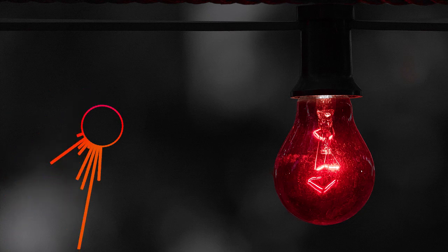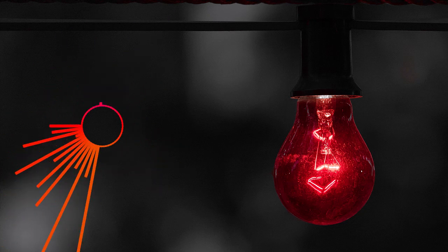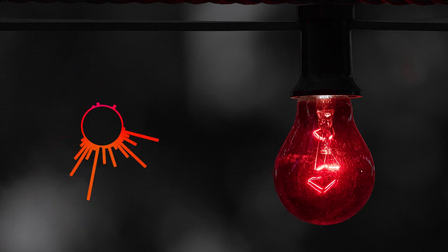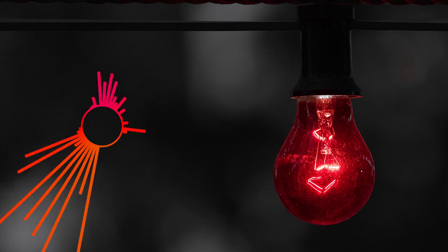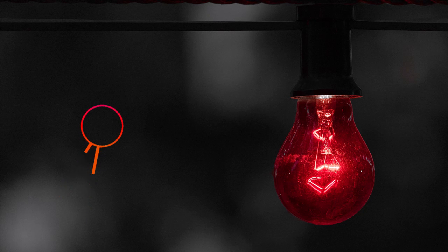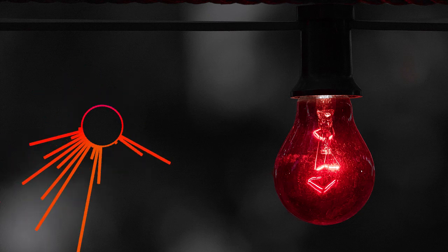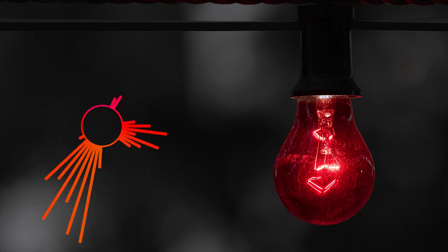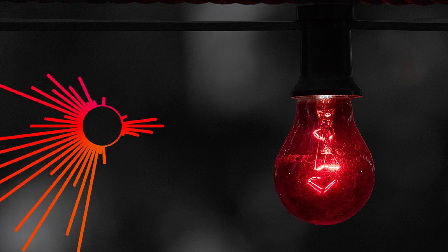Here's a smart one, daylight harvesting. Imagine you're in a room with big windows and it's a sunny day. Do you really need all the electrical lights on? Probably not. Daylight harvesting systems use sensors, also called photosensors, to measure how much natural light is coming into a room.